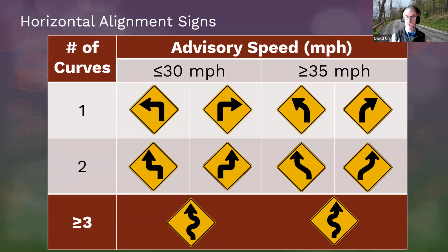That used to be you shall. Okay, now it's a should/may, depending upon how much differential speed you've got. And they did that, I think, in part because some corners that technically are at 30 miles an hour or less, because the approach speeds were pretty small, relative difference wasn't great, it didn't drive the same way as a sharp corner. And remember, we're trying to be uniform in what we tell people. I suspect this is going to get tweaked over time, but just something to be aware of.